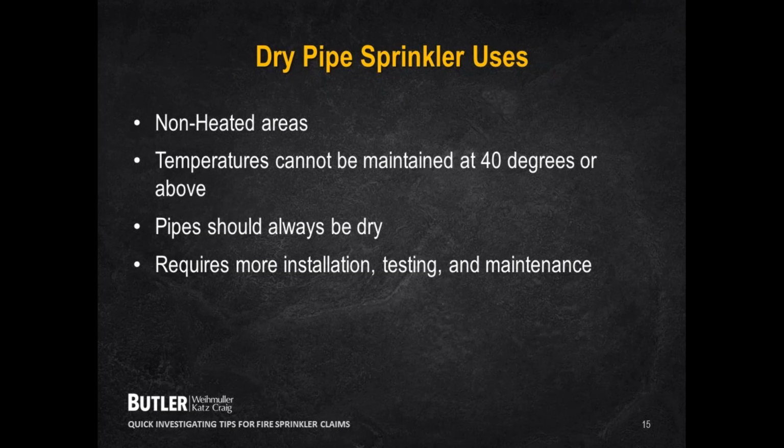There's air pressure inside of the dry pipe. It's not just an empty void space. It's constantly being pressurized by air, and the air holds down a clapper valve and keeps the water back from the pipe itself. Once air pressure is lost because of an activation, like smoke entering the system, then that clapper will fall down and allow the water to flow.